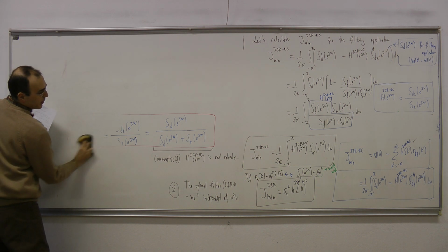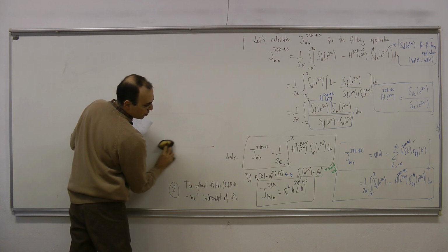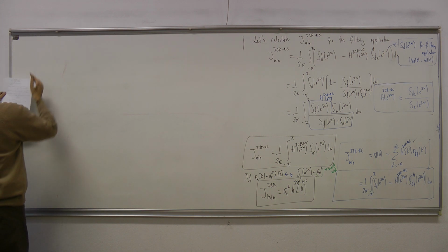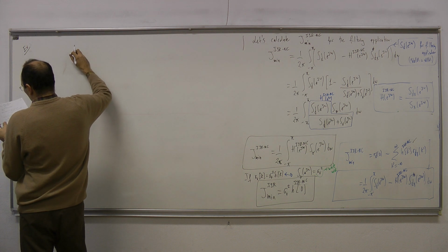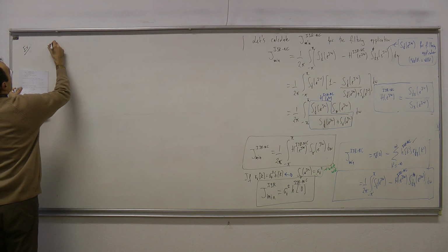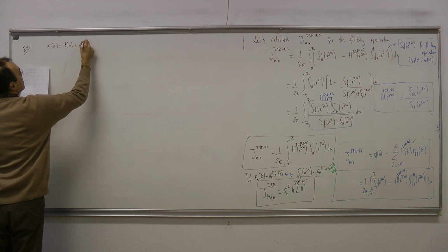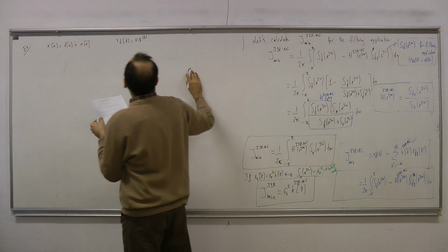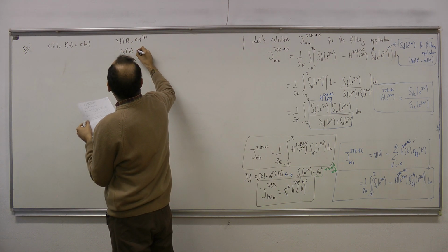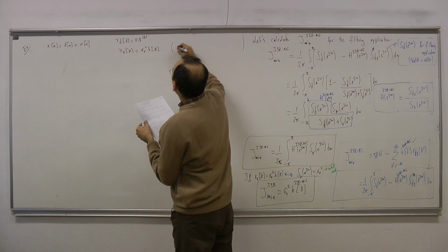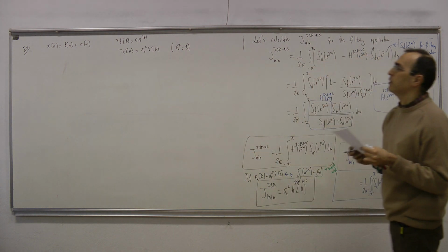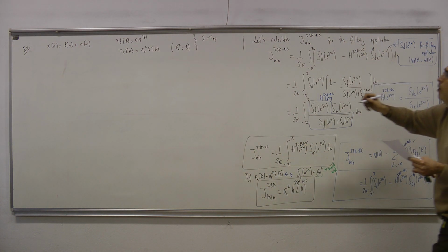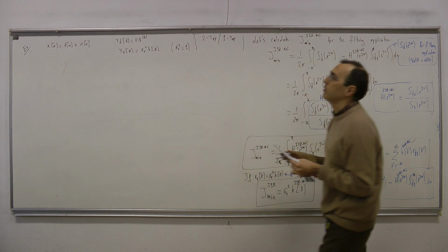So let me have a numerical example on this. Actually, this is one of the examples that we have previously studied. We continue with the same example, but this time we are implementing the FIR Wiener filter. So x of n is d of n plus v of n, then rd of k is 0.8 to the power absolute k, and rv of k is sigma v square delta k, but in this numerical calculation we had previously taken sigma v square equal to 1. Previously we calculated a two-tap FIR Wiener filter and a one-tap FIR Wiener filter for the same one.